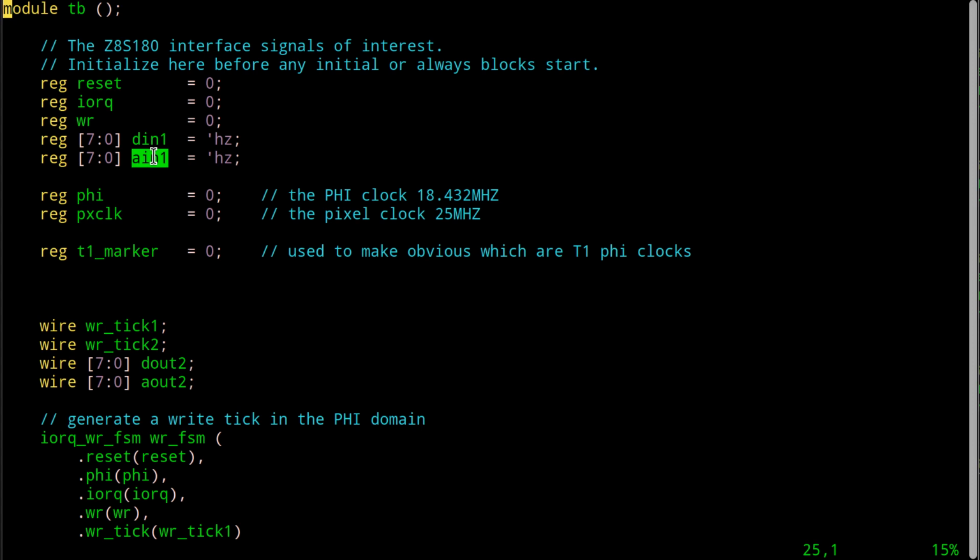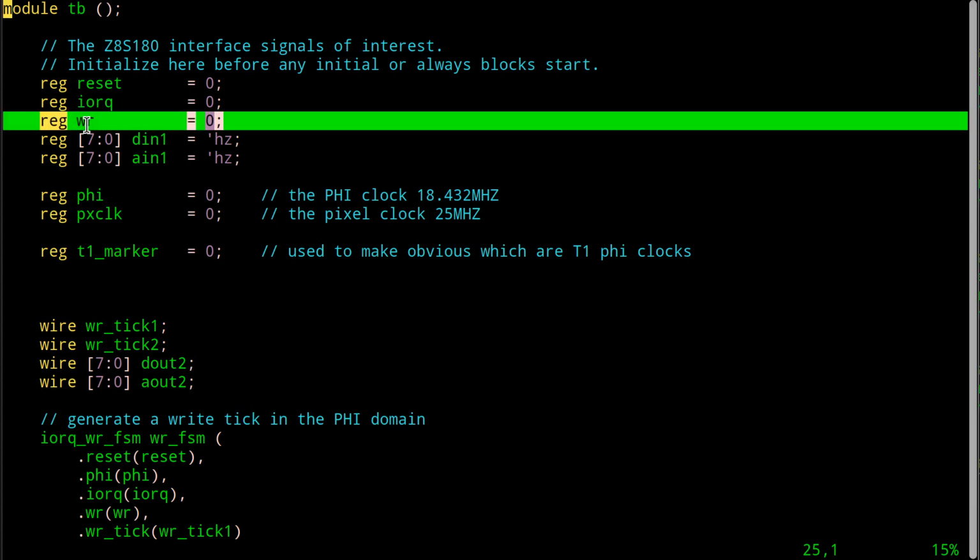The address comes in. I'm only dealing with 8 bits of the address bus for the old school style I/O operations, which used to be 8 bits on a regular old Z80. You can use 16-bit I/O operations on the S180, but that's not my concern right now. So we have an address bus, we have a data bus, we got the I/O rec signal letting us know it's an I/O request, and we're outputting from the CPU, inputting into our FPGA.